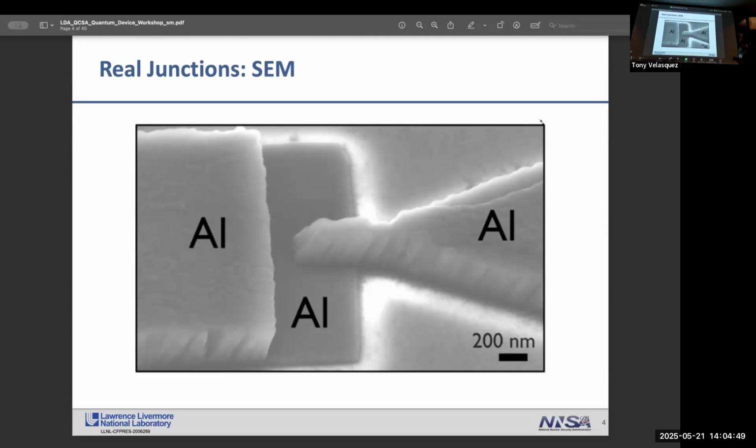For the purpose of bandgap engineering, it's quite common to have a very thin lower electrode layer of aluminum, with some nice work from Google recently about that, and then a much thicker top electrode. You can see, by eye, that these are very different kinds of systems: the thin layer versus this very grainy top aluminum layer.